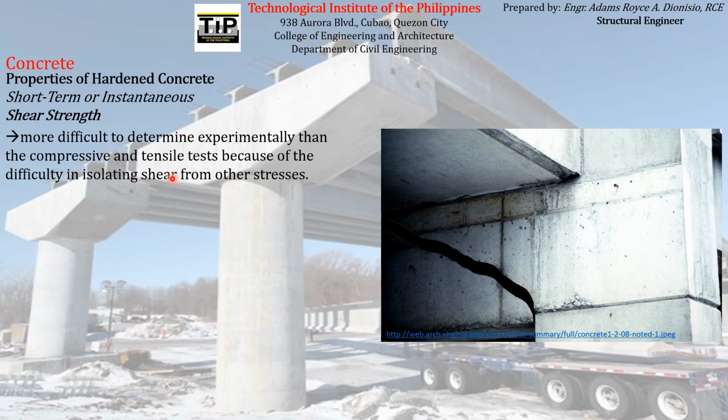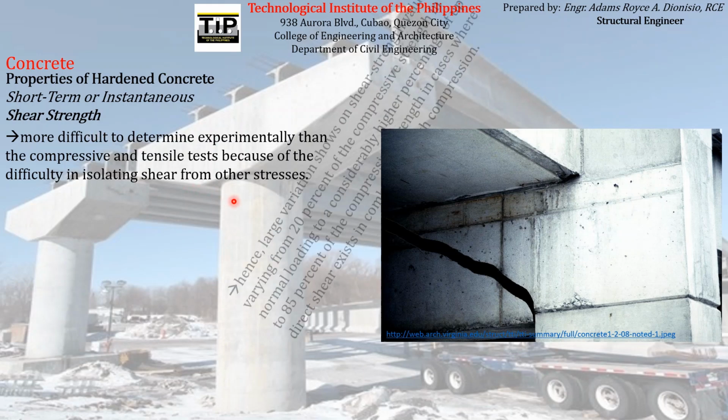That is a major problem here because we cannot induce pure shear stresses on a concrete, because shear stresses usually occur together with other stresses like axial stresses, compressive stresses, tensile stresses, and or bending stresses. So we cannot isolate shear alone to be able to measure the shear strength of concrete.